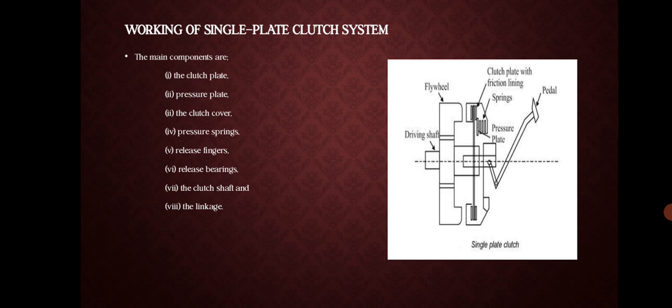Thus, the condition of disengagement remains till the clutch pedal remains depressed. The moment the pedal returns to the engaged position, the pressure plate moves ahead to press the clutch plate due to the pressure springs.